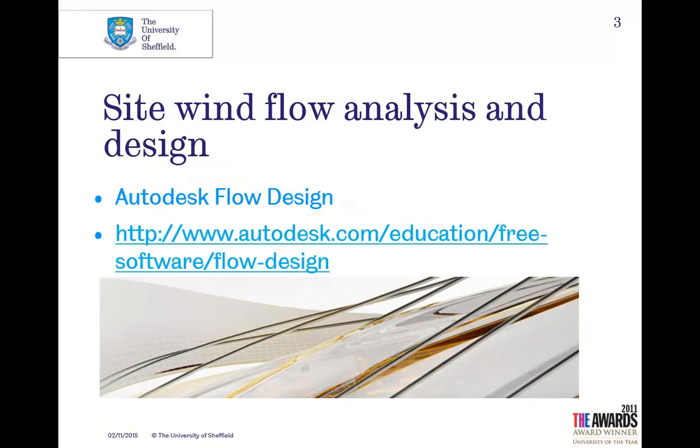Now, this is an area of software which has been changing every year. Two years ago we did this simulation in Autodesk Vasari. Last year we were doing it in Project Falcon, another Autodesk product, and we were doing it in the Flow Design plugin for Revit. But it's changed again this year. So in Revit 2016, the Flow Design plugin has come back out again. So we now do this simulation in Autodesk Flow Design as a standalone piece of software.